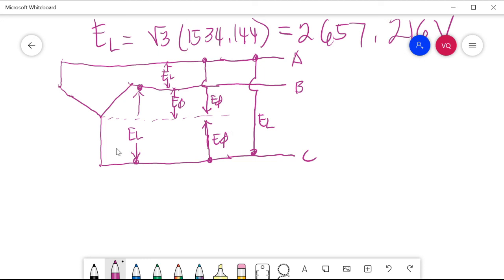So this is the schematic or circuit diagram of a Y-connected alternator. I assume that you already discussed this in your Circuits 2 in polyphase, so I will not discuss this any further. This is your ground or neutral, this broken line here, and you have your 3 lines, lines A, B, and C. The line-to-line voltages, or the E line, are EAB, EBC, ECA for the positive sequence.